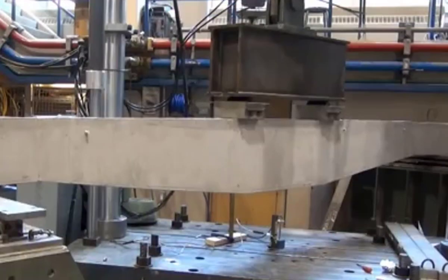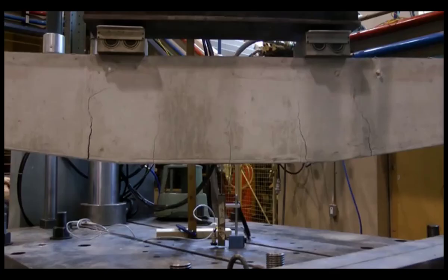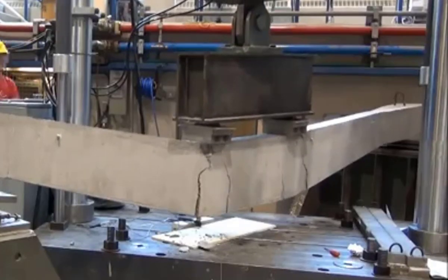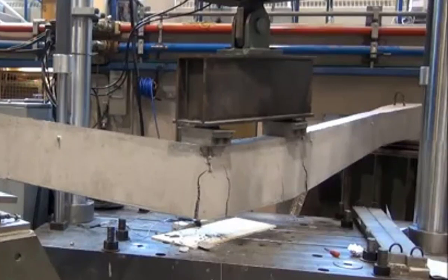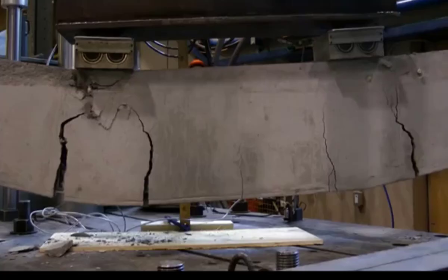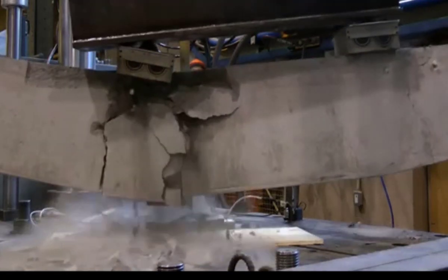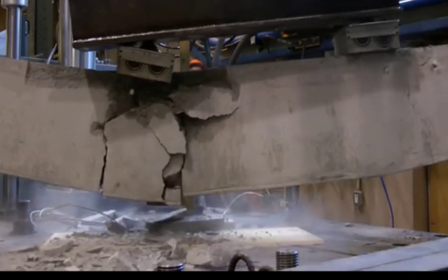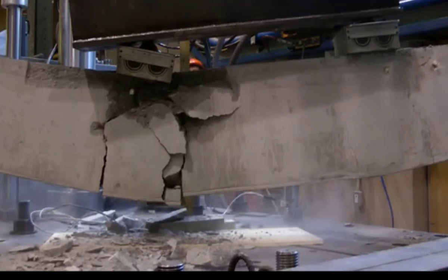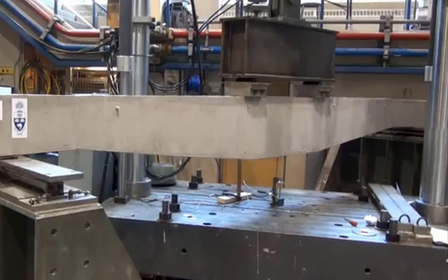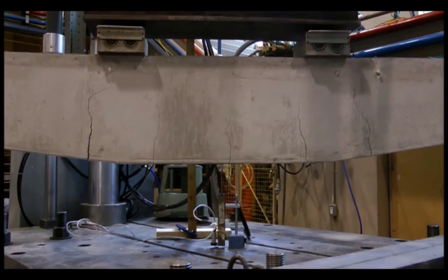For instance, if a beam wants to fail in shear, it will do so in the following process. First of all, it will start cracking from the bottom to the top. Cracking will take place. That's the first. Then the second process, it will start deflecting a little bit, and gradually it will be twisting. That's torsion, and then finally it will shear. The most critical limit state here is shear. Therefore, I can just design this beam for shear. So you don't need to design it for cracking, deflection, twisting, and shear. Just design it for shear, and in the process, the rest will be taken care of.